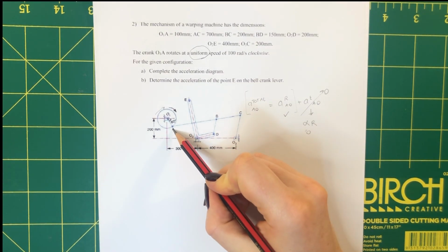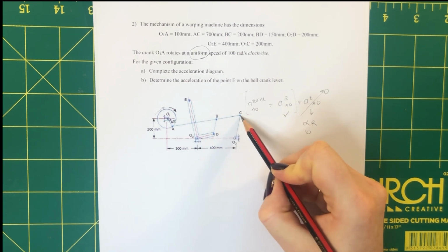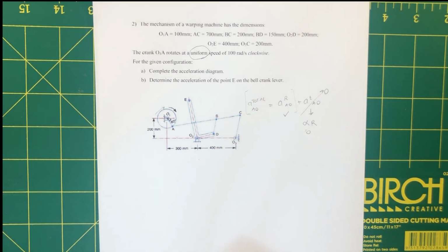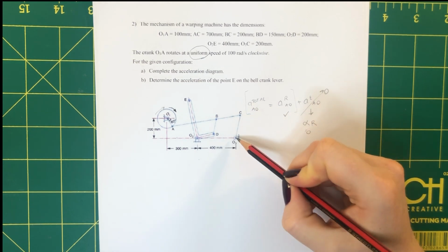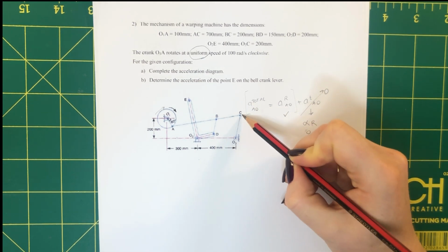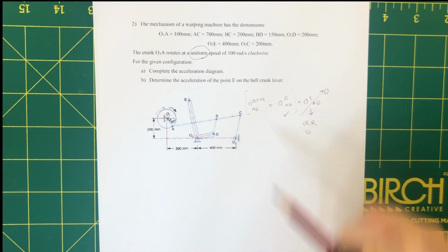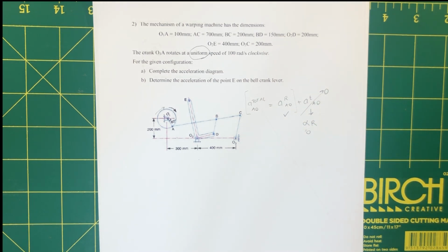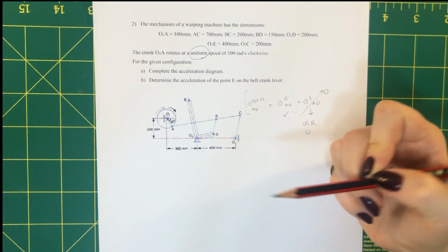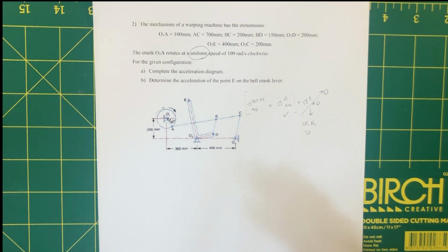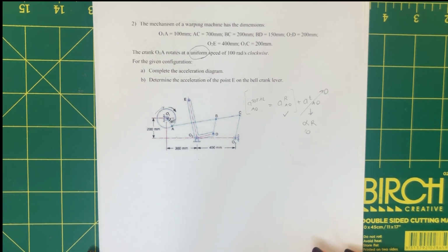Now we move on to the second point in the diagram. You can see that point A is connected to point B and point C as they're all on the same link. We're going to find point C first because point C is connected to another fixed point, O3. If you choose point B to find, you'll have to draw about 6 lines to find point B. However, to find point C, because it has that fixed point, we only need to draw 4. So we're choosing the next easiest point to help us construct our diagram.